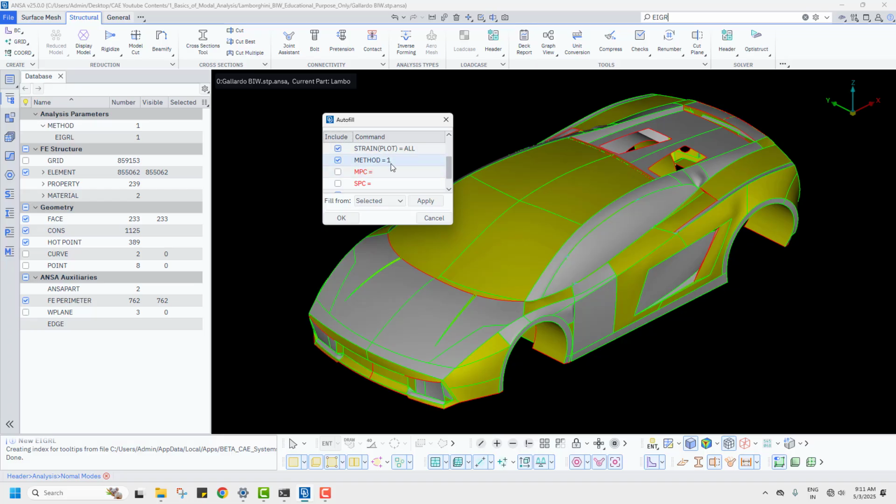And then the method, structural, it is taking, okay. Now one parameter card it is adding, PARAM POST -1, okay. Now if you want to refer more about the parameter cards, you can go to the OptiStruct help and refer to param cards, and then it will explain all that. Okay, PARAM AUTOSPC, okay, PARAM INREL -2, and then the element check option, yes or no.